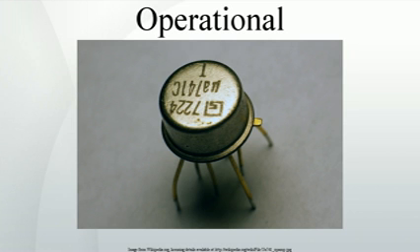External overall positive feedback may be applied but, unlike internal positive feedback that may be applied within the latter stages of a purpose-designed comparator, this markedly affects the accuracy of the zero-crossing detection point. Using a general-purpose op-amp, for example, the frequency of V_I for the sine-to-square wave converter should probably be below 100 Hz.